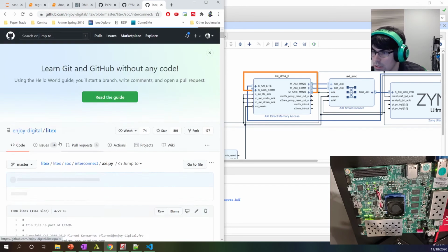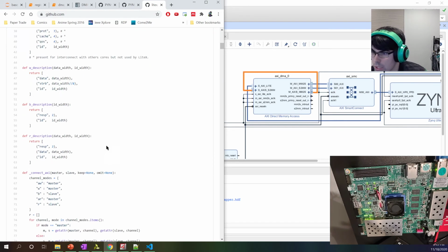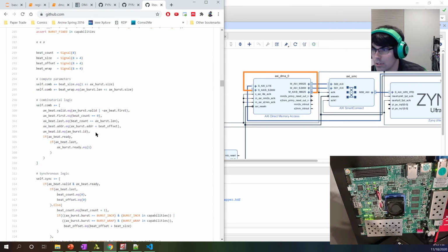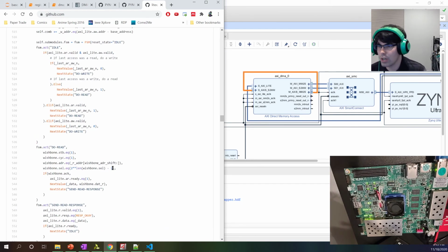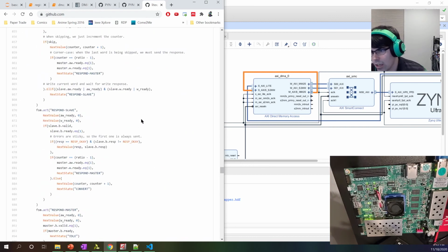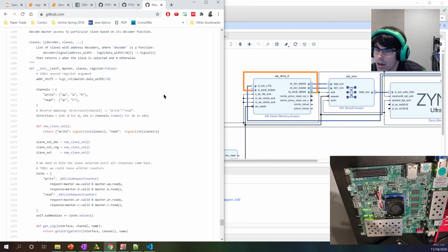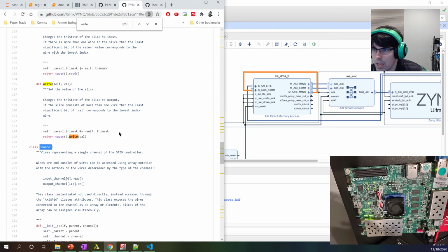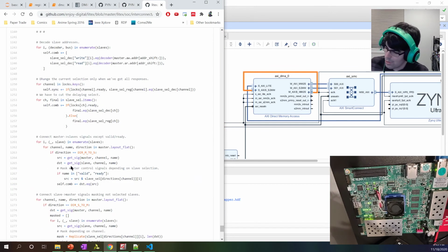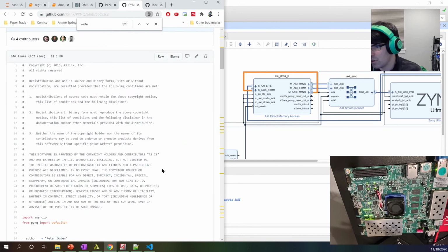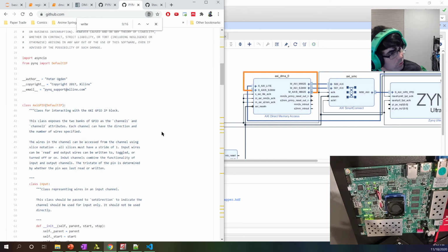So we probably want to get an AXI to Wishbone converter, and then play around with AXI-Light to Wishbone. Perfect. That way we can try to incorporate LiteX with PYNQ. I think that could be very powerful for testing and for running things. And if we could get the PYNQ software running on the VexRiscv processor or another RISC-V processor, that'd be really cool. We'll see how that goes. That's not going to happen anytime soon, but it seems exciting.